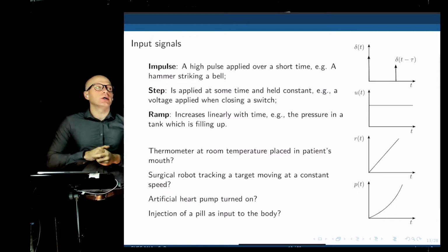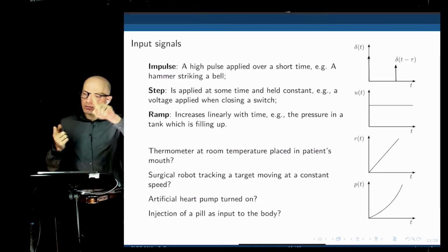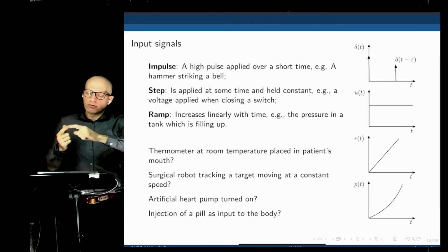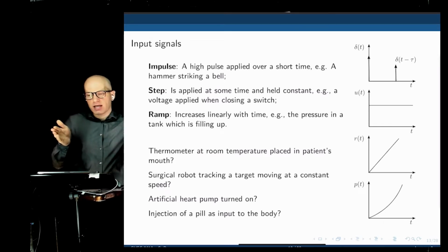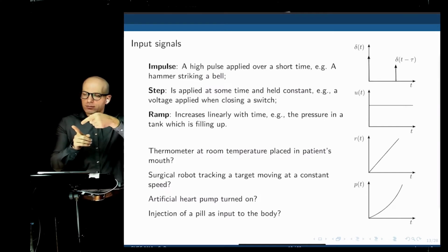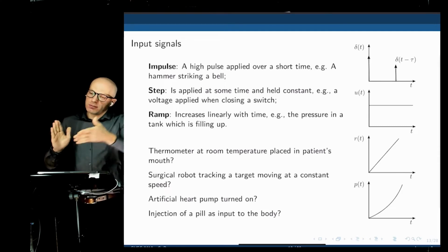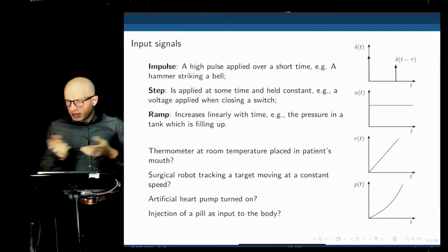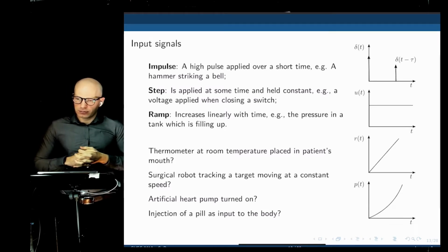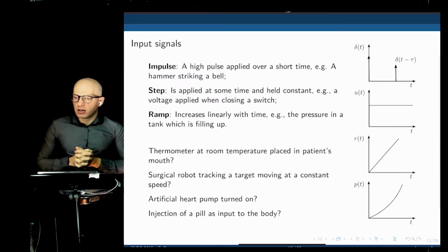If we now tell the robot, move along this trajectory that is increasing over time, follow this thing that is moving at 5 millimeters per second. So point 1 will be here, at time 2 will be here, at time 3 there, and so on and so on. Our reference position keeps moving and increasing over time. That would be a ramp. Tracking the distance would be a ramp. Keeping a constant speed would be a step.